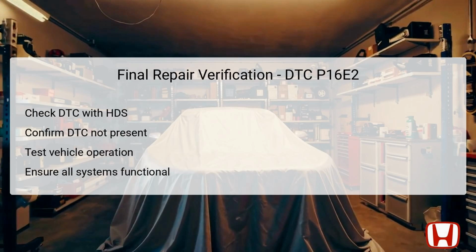After completing repairs, based on the previous troubleshooting steps, it is vital to verify that the issue has been resolved. This starts by checking the DTC with the HDS to ensure that DTC P16E2 is no longer present. Confirming the DTC is cleared is essential, as it indicates that the issue has been successfully addressed.